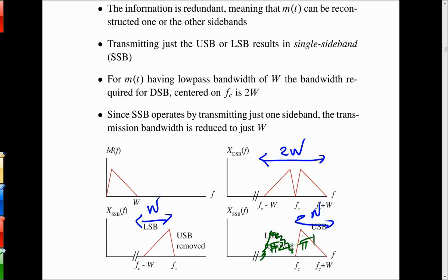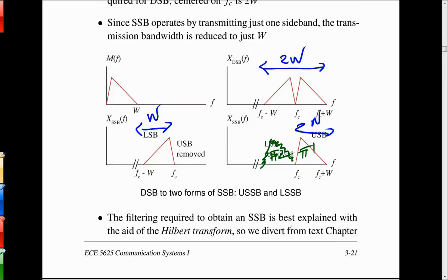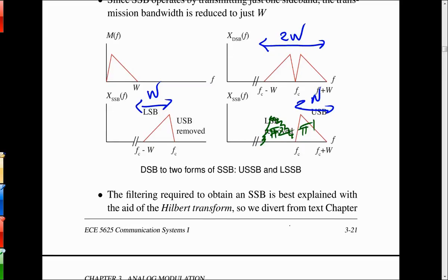This is what the telephone company did for decades and decades on wired lines. This is how the switching center took the information from the home and relayed it across the country by microwave tower before we had digital fiber optic means. Everything was done with a hierarchy, and everything was done in this fashion where they used single sideband because they could double the capacity that way. It's still used for shortwave, and it's used by amateur radio people, and it's got certain specialized applications.